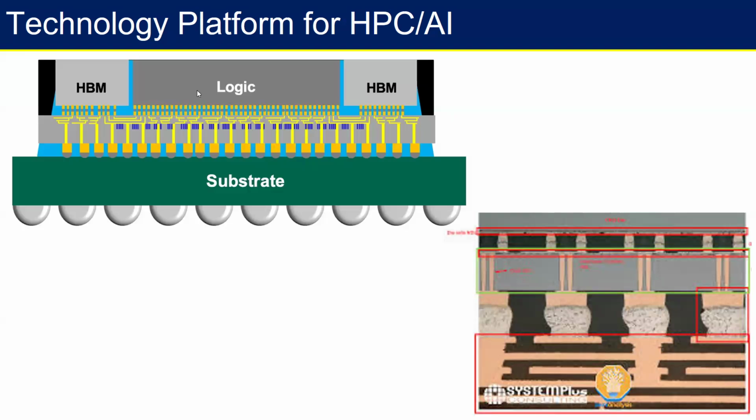What we need here, when the logic is talking to memory, is very good bandwidth. That means we cannot bear latency. Speed is of paramount importance when the logic is talking to memory. So that's why copper has been the workhorse inside the die, in how different transistors talk to each other. So this is always based on what we have learned in the last 20-30 years from copper.